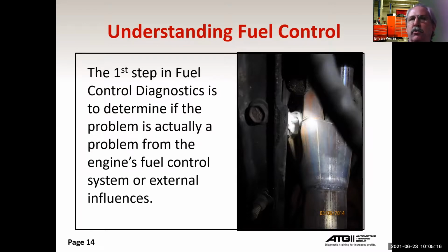It's not a structural crack most of the time, unless you have bad motor mounts or something pulling on something. Normally it's a heat crack. The metal's crystallized some. So it's just a matter of controlling the heat on the weld, and you can weld over a lot of that stuff.